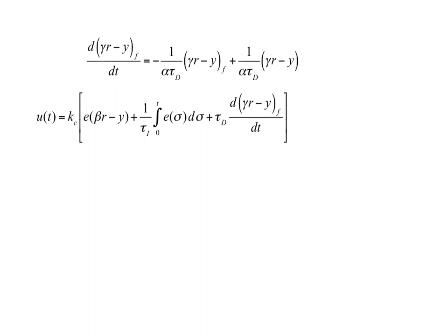In this final slide, we see additional parameters. So what we've done is we've captured this filter time constant as some value alpha times the derivative time, and alpha is usually around 0.1 to sometimes as low as 0.01. So somewhere in that range. I often use about 0.1.